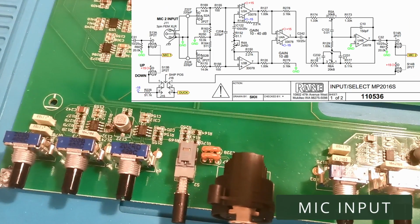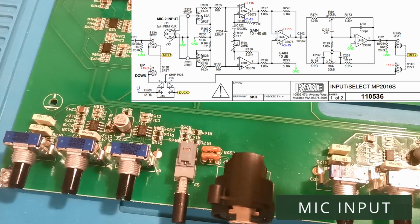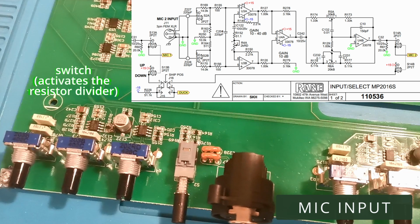First, based on what we see, I will tell you how to read the symbols on electrical schematics. Every physical part is visible on the schematic. First basic part is resistor. It limits the current. The resistor shown sets the input impedance. Capacitor, the second basic part, stores the charge. Here it's a part of high frequency filter. The switch activates 30 dB attenuator.